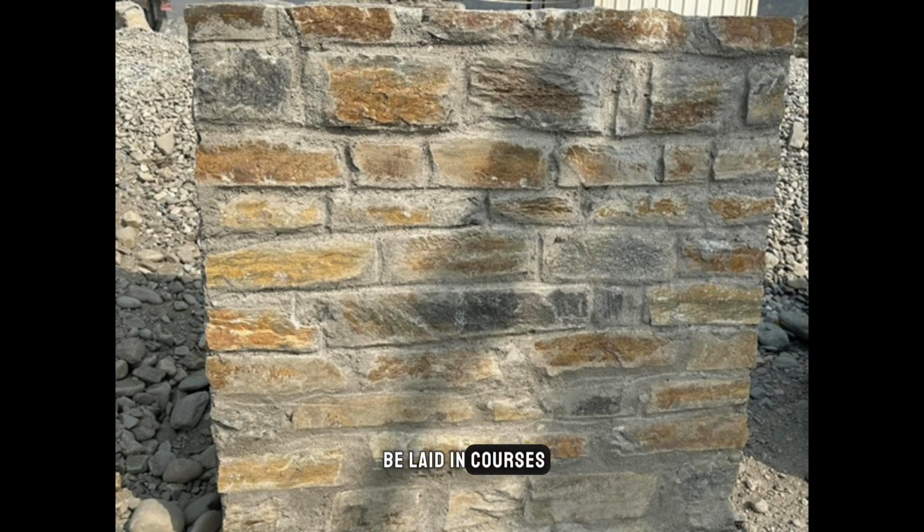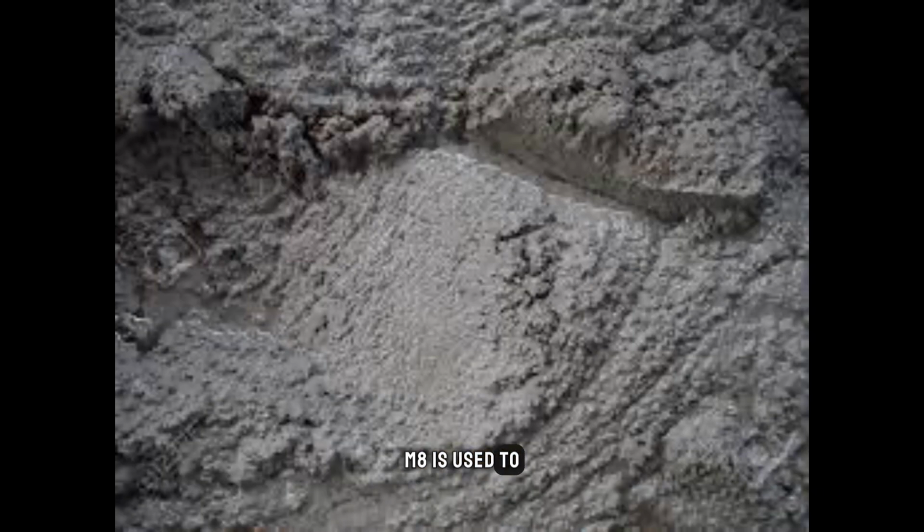The stones are to be laid in courses of equal layers, and the joints should also be uniform. Vertical joints shall be staggered as far as possible, and should not exceed 200 mm depth. All joints shall be full of mortar. The maximum thickness of joints shall be 20 mm for random rubble and 10 mm for square rubble. A cement mortar of grade MM8 is used to fill the joints and the gaps between the stones arranged.